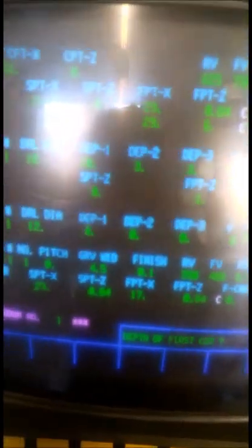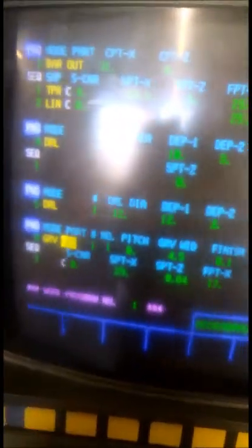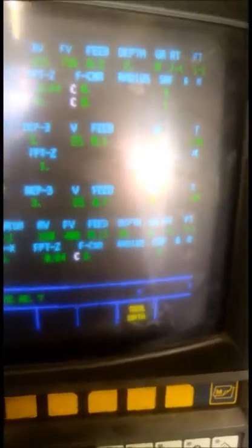We want to do another drilling op. Number 1 again. 12 mil, so this is my actual drill that I'm putting through the hole. We'll just auto all of that. Happy with all that. And this is tool number 5. Insert another line.